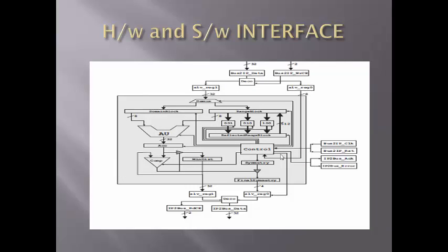At the same time, it was necessary to add the control signal to integrate the TCU into the communication protocol of the peripheral bus. So after finishing the hardware and software interface, we are going to create a computational system on the FPGA with the embedded PowerPC 405 processor, and the whole system is kept inside a single system on chip for writing the files, read, write, the control block, everything. We are going to use a FAT32 file system and many other components, which form a single system on chip.